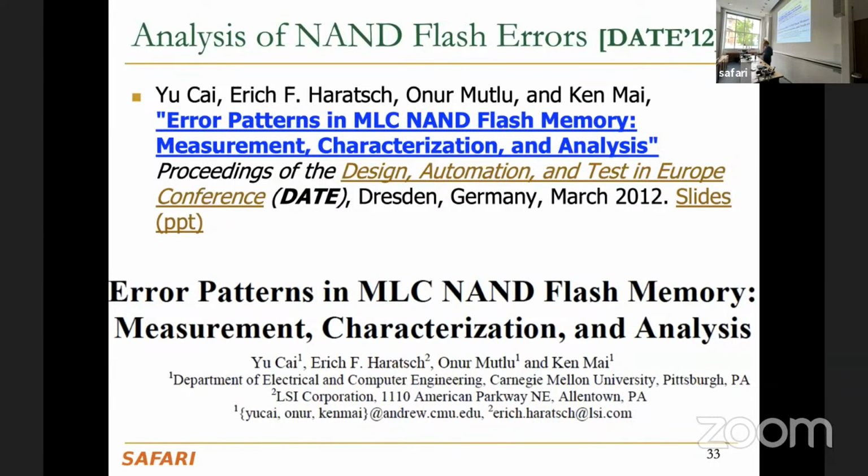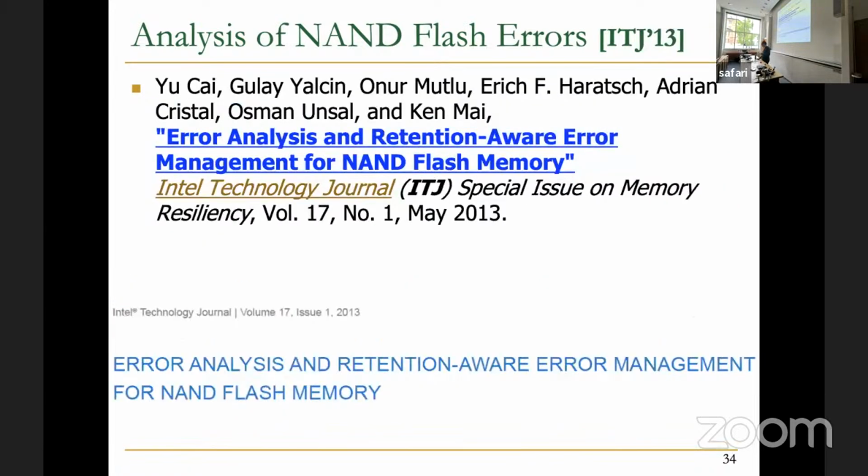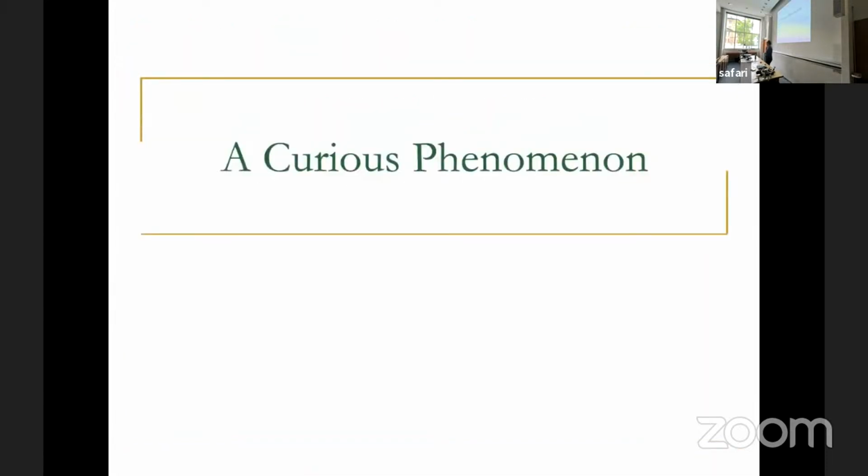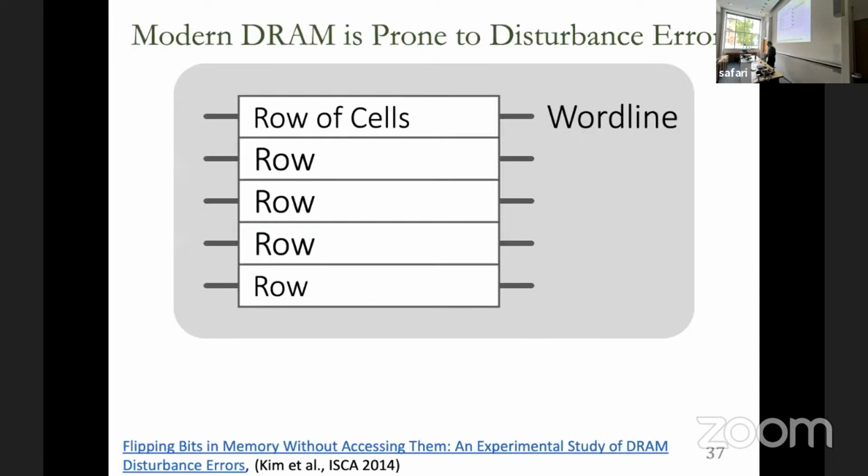And then, of course, if you're doing these things, the natural question to ask is, what about other issues in DRAM, right? DRAM clearly does not have only retention issues. These other memories have read disturbance. What about the read disturbance in DRAM? Let's analyze that. Let's see if there's a problem, and let's understand if we can solve it. And that's what we essentially did to understand. Essentially, that's what led to RowHammer. And we did this together with Intel folks who actually helped us build some of that infrastructure. So what is RowHammer? Essentially, you can produce these bit flips internally in DRAM. And the idea is very simple.